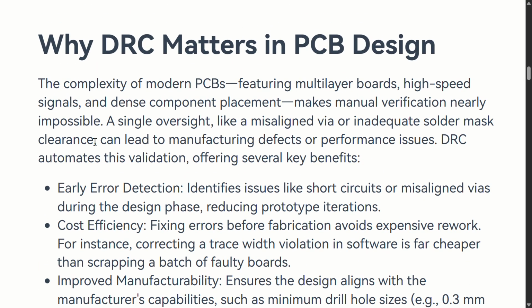So why does DRC matter in PCB design? As technology is advancing, we are seeing multi-layered PCBs and high-speed signal data transmission, the 50 ohm rule, and we are coming to impedance. The component placement in a PCB is getting denser and closer, trying to fit everything in a small place. But still you need to follow DRCs. Why? Because those DRCs are proposed based on multiple experimentations.